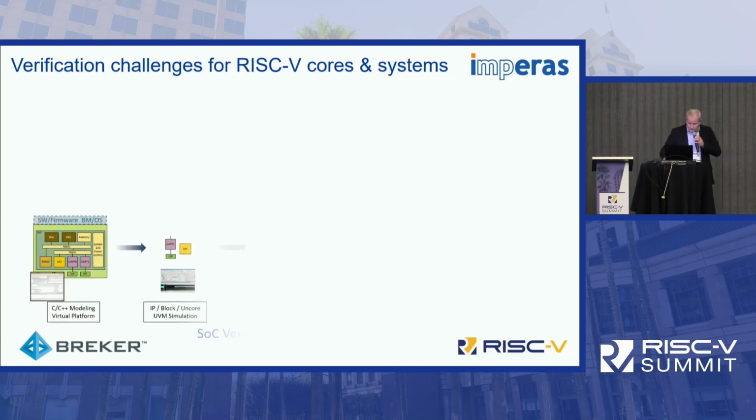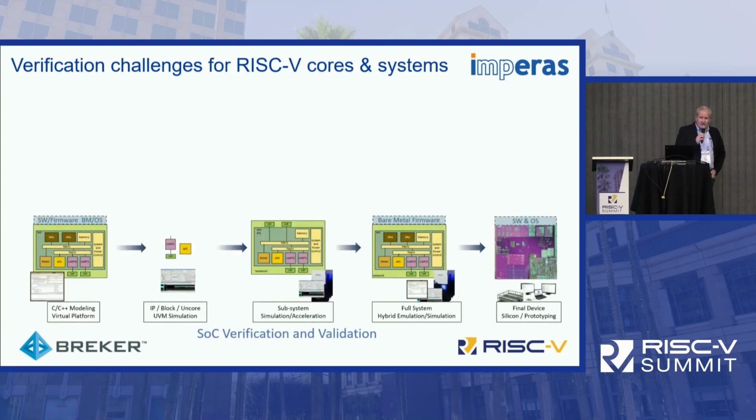Now, as we know, there is already a process in place for SoC design, and this is what we see, whereby an initial design is done in C, C++ modeling, and then there is a bottom-up bring-up approach whereby you have simulations of blocks, you tie the blocks together in a subsystem, and then a full system simulation, ending up in final device silicon.